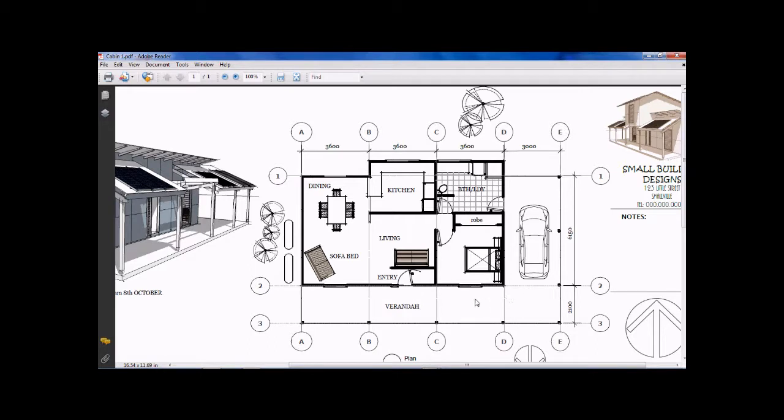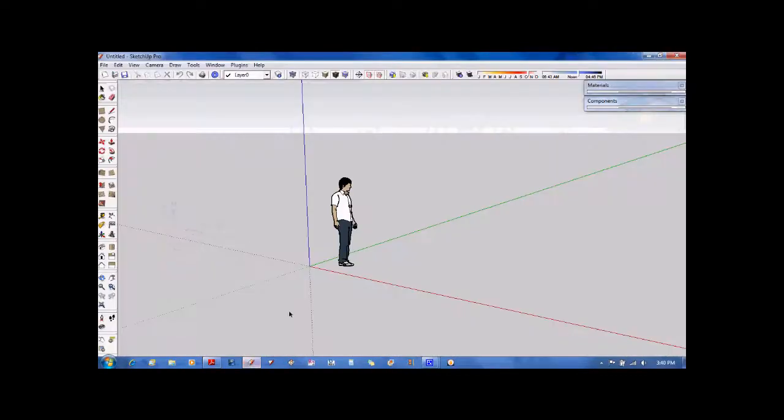way of thinking. Likewise, along the gabled end of the building, I'm envisaging using something like vertically orientated corrugated steel, zinc aluminum or Colorbond corrugated steel. And if you care to sit down and work out the modules that steel becomes available in, you'll soon see that a 6.15 metre width of the building also suits that with no cutting or sheet wasting. So with this bit of a view in mind, we'll open up SketchUp and start laying a few things out.